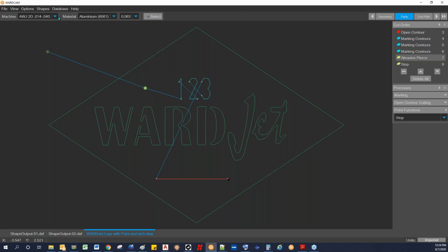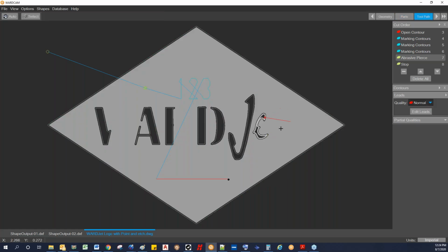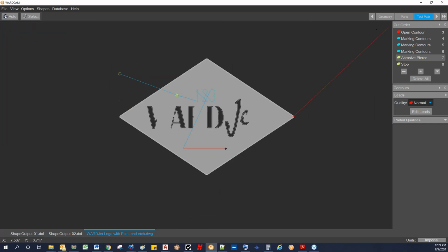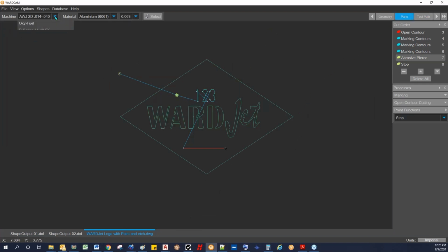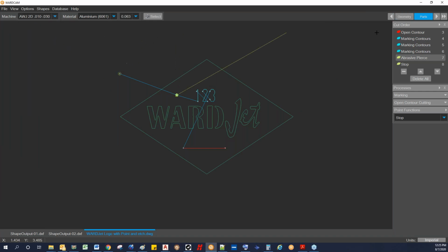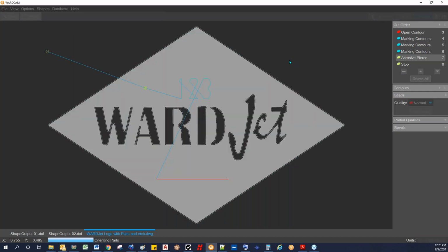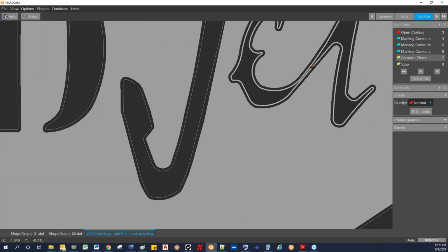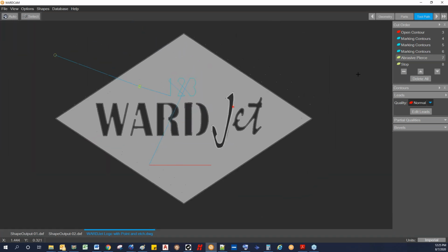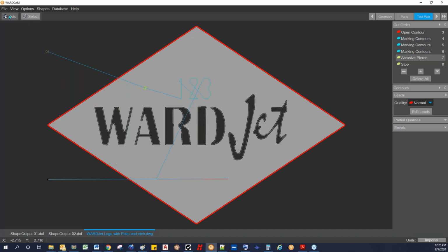Now, because of a 1440 nozzle combination selected right now, when I've been going to this toolpath area, it's not showing the rest of the geometry here because it's looking at this gap here, and the gap is smaller than the tool diameter that I've given it. So if I switch to a smaller nozzle orifice combination like a 1030, that should be small enough, and I hit next, and then you'll see now that we can get through those areas there because the gap is wider than our kerf width. And then if I want to put my Toolpaths on here, I can click Auto.